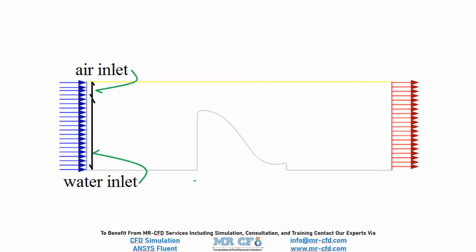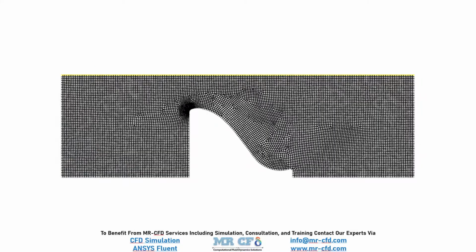The 2D geometry of the present model is designed by Design Modeler software. The present model involves a wide-angle overflow that comprises a vertical wall in the flow path. Also, the meshing of the present project is carried out using ANSYS meshing software and the mesh type is unstructured. The element number is equal to 10,959.